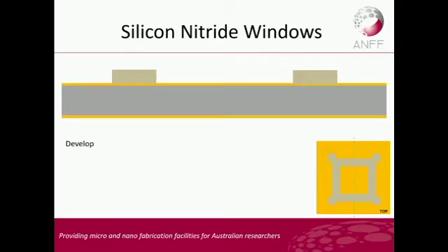And then we put it into the RIE. So we've got an RIE and a DRIE, and again, Kai will talk about the difference between the two later. So we etch through the silicon nitride. So we've exposed the silicon on one side only. The other side is protected. And then we can dump that whole thing into KOH, and we can etch all the way through the silicon. It takes, when I say quickly, about 10 hours to go through, say, 500 microns.